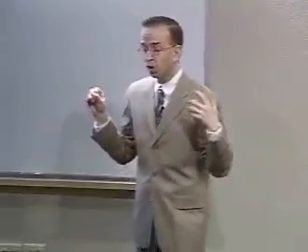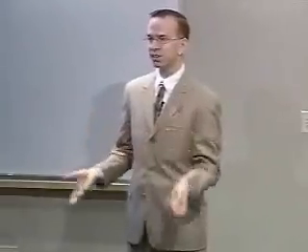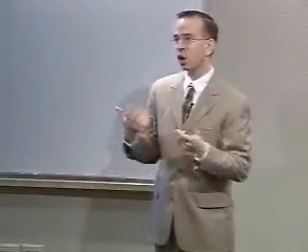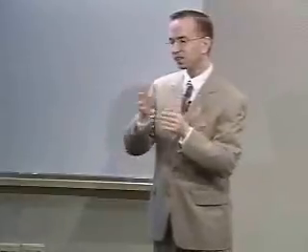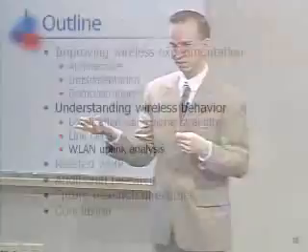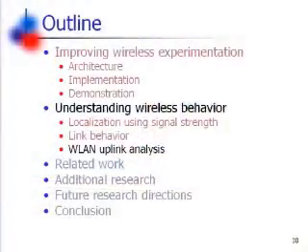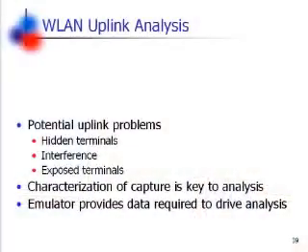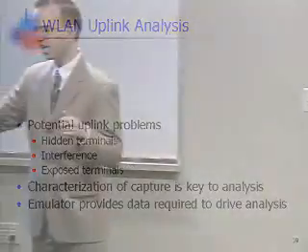Okay. So I'm not going to show this next result just in the interest of time, but basically I measured packet capture where we wanted both signals. In this case we have two transmitters and a receiver, and we potentially want packets from both of them. What signal margin, how much stronger does one of them need to be than the other in order to successfully receive its packets? We were able to characterize this, again, using an emulator. I'll get back to that if people are interested. What we did is use this capture data to drive an offline analysis.